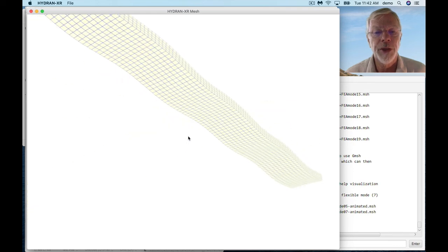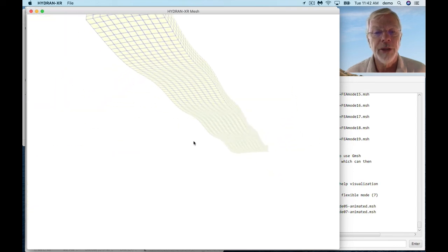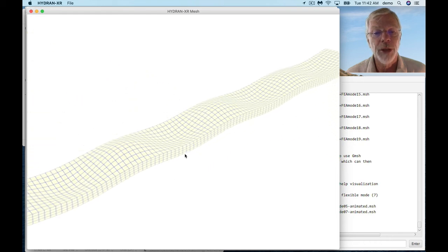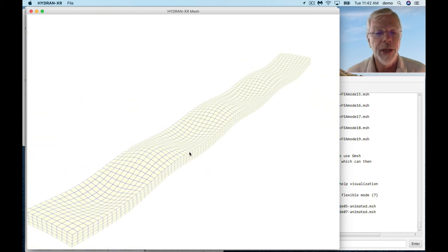You can see that it's the top plate that's having these kinds of behavior predominantly, and that's because we put so much of the mass on that top plate, if you'll recall. So probably not what you would see in a practical structure, but these are the kinds of modes that you want to avoid. We would have seen these a lot sooner if we hadn't used a bending stiffness or appropriate stiffeners.